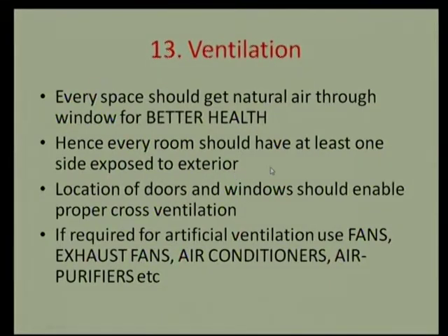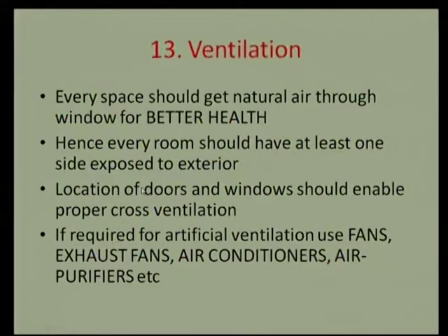So at least one side should be exposed, even if it is a servant room or a storeroom. A storeroom also should have at least one side, out of four sides, facing the external environment, so that we can provide a ventilator on the side which is facing the exterior. Location of doors and windows should enable proper cross ventilation. So cross ventilation again is very important.